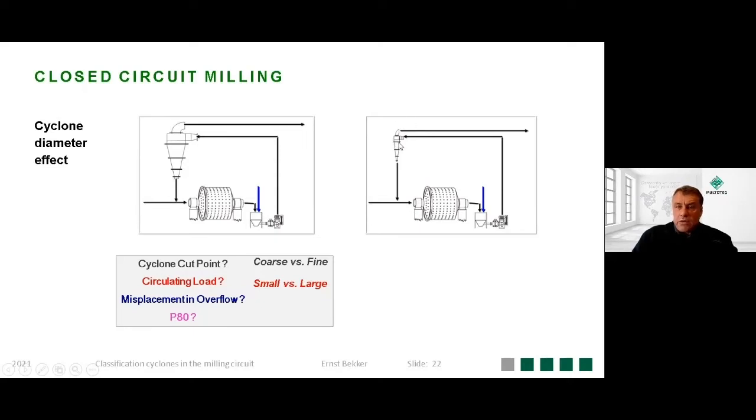The small cyclone has got a high circulating load because all the material that's initially entering keeps on going back to the mill. And that cannot also be the case. You cannot keep material inside the milling circuit. It needs to reach equilibrium. So eventually the feed density increases to such an extent, because now there's such a high circulating load of solids, you have to cut back on almost all the water, that the feed density then forces this cut point to become coarser, and eventually the circuit will stabilize.